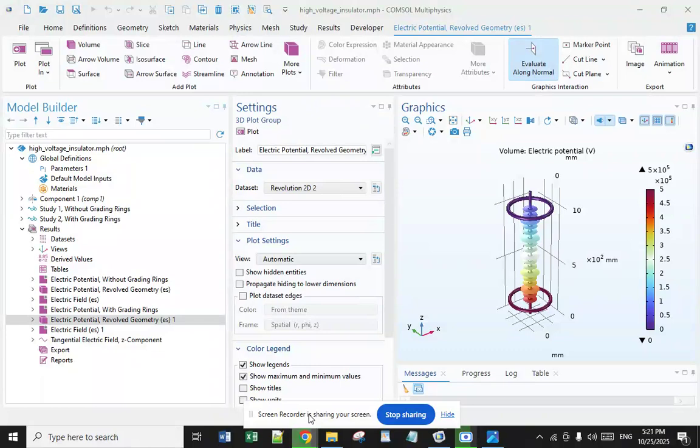Porcelain insulator. Porcelain insulators are the most common type of insulators in high voltage lines and are used in transmission towers and poles. Porcelain insulators are resistant to heat and wear and have a long service life. And what about glass insulators? Glass insulators are used in low and medium voltage lines as well as in transformers. Glass insulators are weather and corrosion resistant and are very efficient in preventing short circuit.